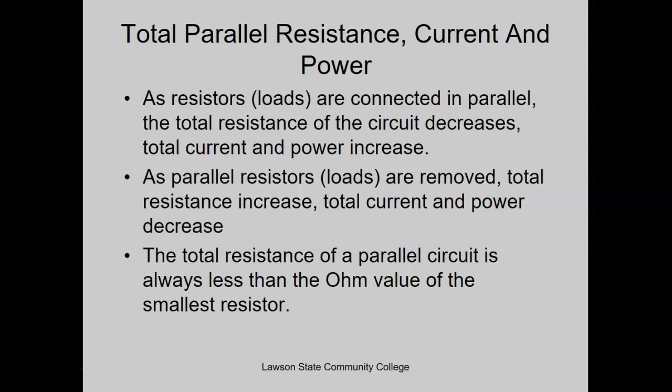That is the point. The total might change, but the individuals can't. You have a parallel circuit. The individuals will not change. Your voltage cannot change because it's parallel. What stays constant through a parallel circuit? Voltage. If your voltage doesn't change, can your resistor change value? No, your resistor cannot change value because your resistor is a fixed resistor.